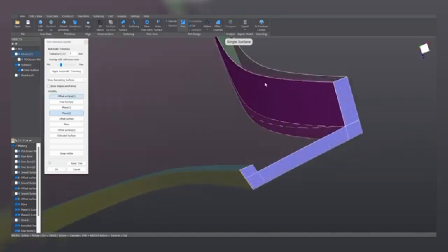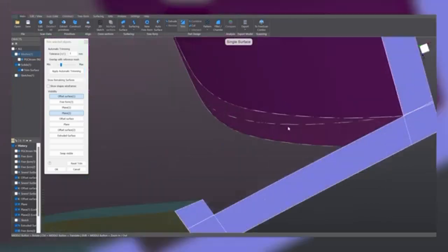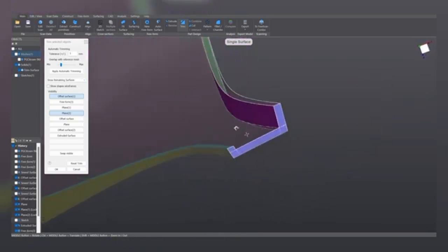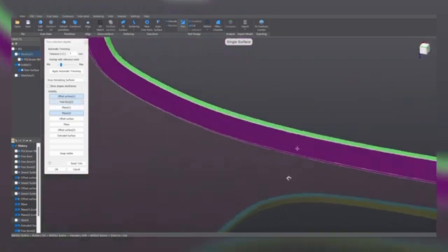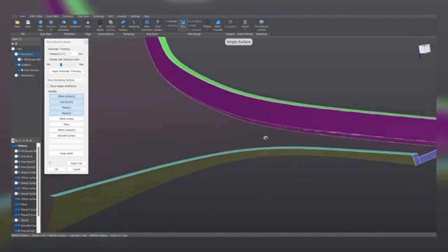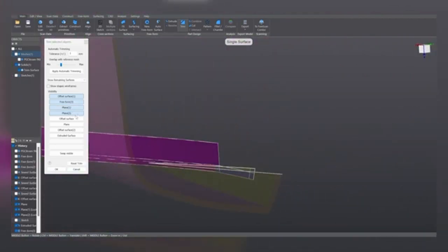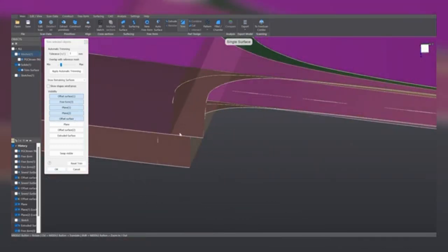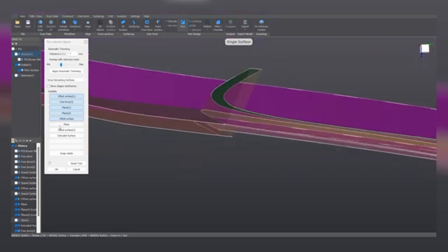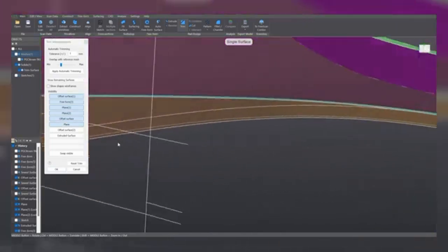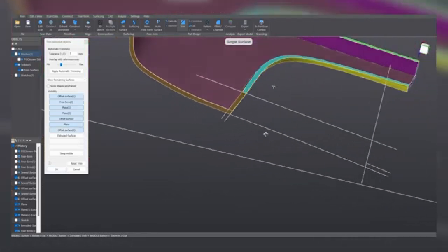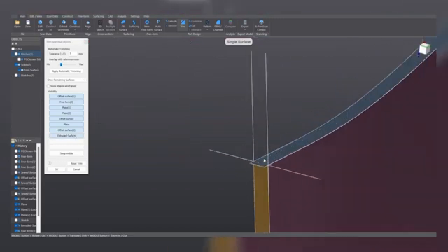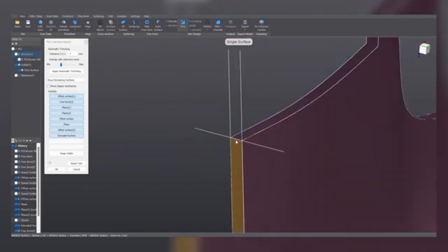Here we have exactly the same problem that we described. The surface on the left is going into the volume of the solid, so delete these faces. Okay, this looks clear. This plane looks good, no problems with it. The offset surface, watch out, it's going into the volume, so we need to delete this region. The plane here is well defined and well trimmed. Same for this offset, and well, we have this extruded surface, which unfortunately leads to this problem, right?